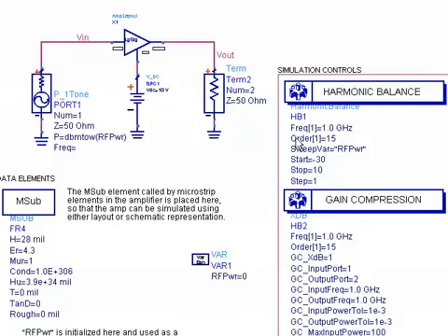So this is a sweep with 15 harmonics, and you'll get that data. But the gain compression, or XdB controller, which is also harmonic balance, requires 2 ports for the input and the output, and that's what you see here, 1 and 2. And that's why we have a 50 ohm termination here instead of a resistor, because it has to have this num equals so we can specify. That's port 2 and that's port 1.